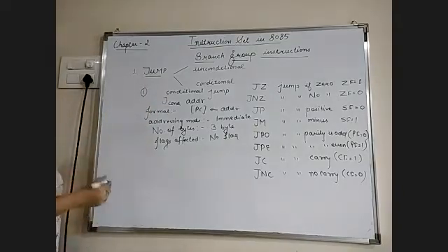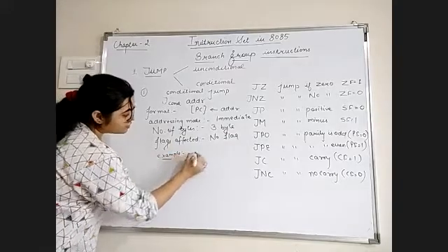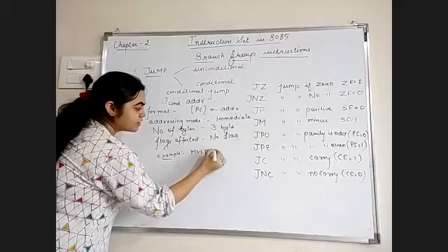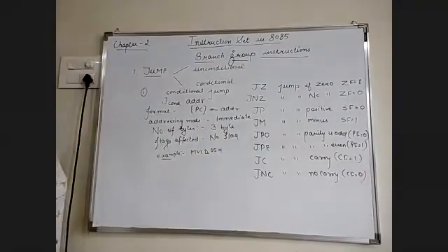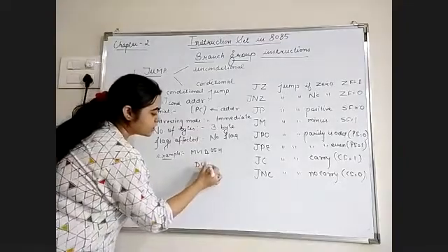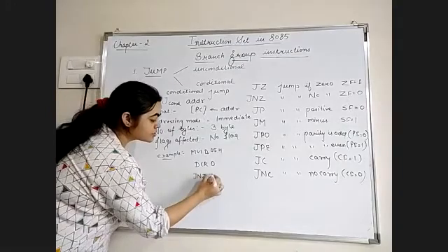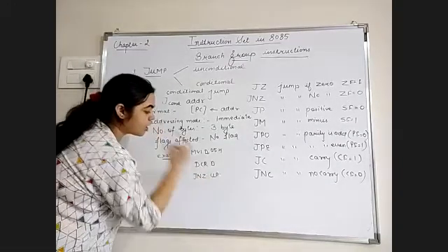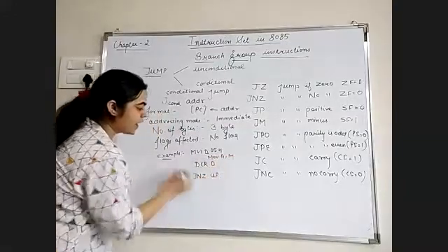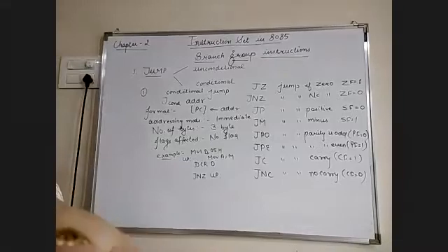So here, for example, we have an instruction. Initially, I am assigning the D register a value, suppose MVI D, 05H. After this, I am writing DCR D. Then I am writing the condition JNZ UP. And here I am writing some instructions, suppose MOV A, M. And UP we have here. Okay. Just a minute.